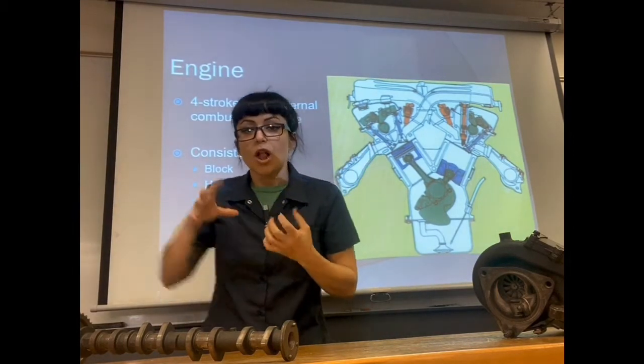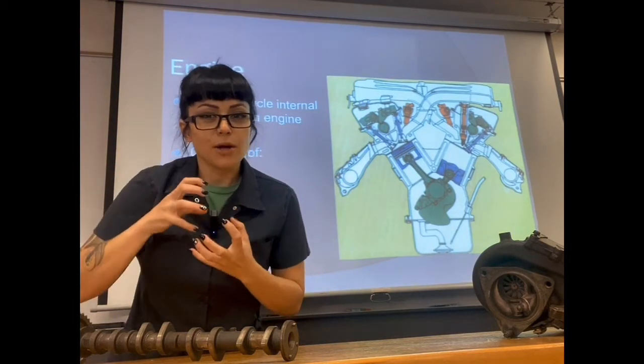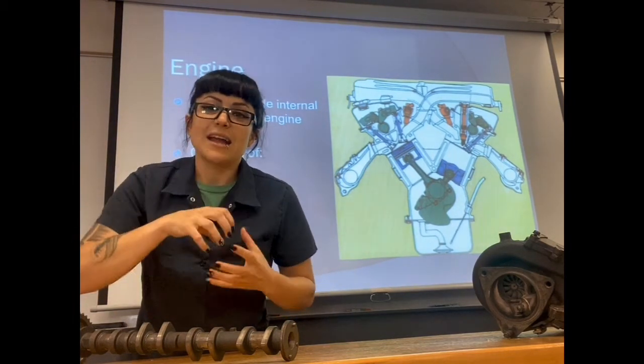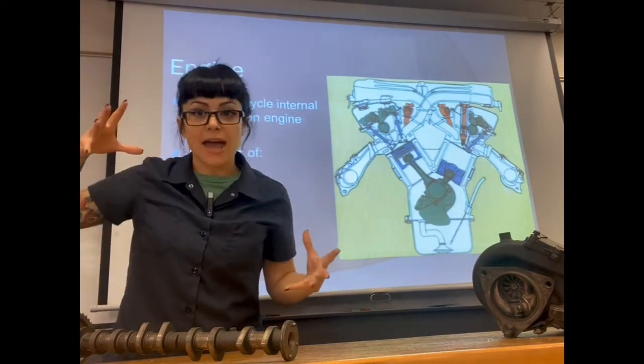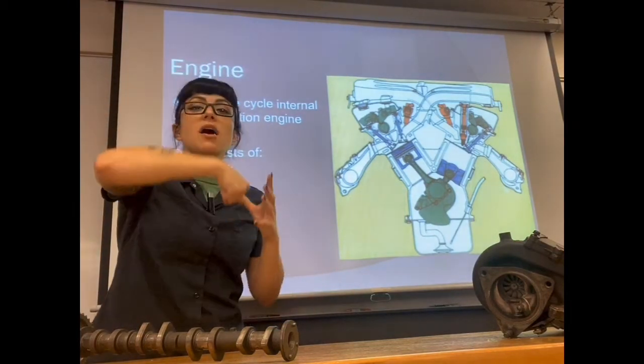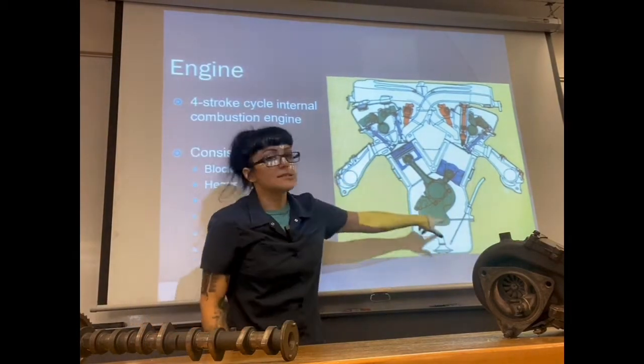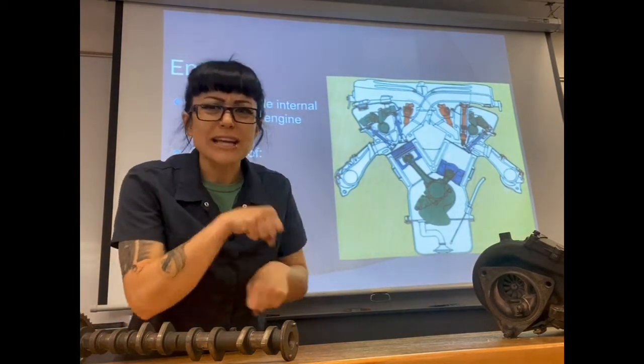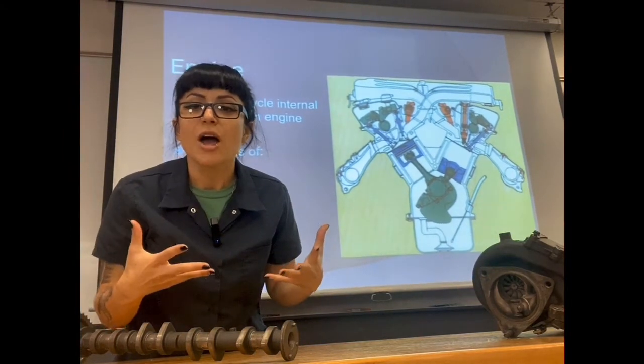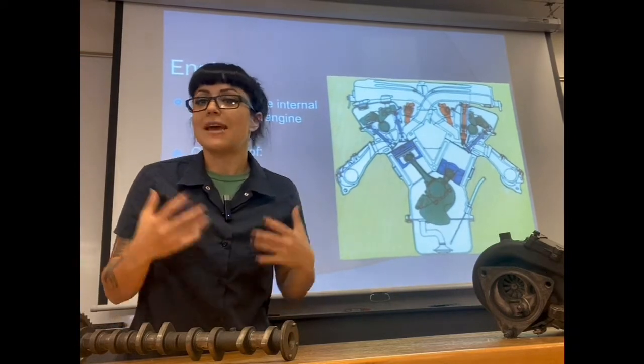But that is our engine, and the way things work inside is we suck in some air as well as some fuel. We squeeze that air and fuel, we ignite that air and fuel, and that explosion that happens is going to shove down these pistons, and we're essentially going to be turning some bicycle pedals, right? So our crankshaft is essentially a set of bicycle pedals.